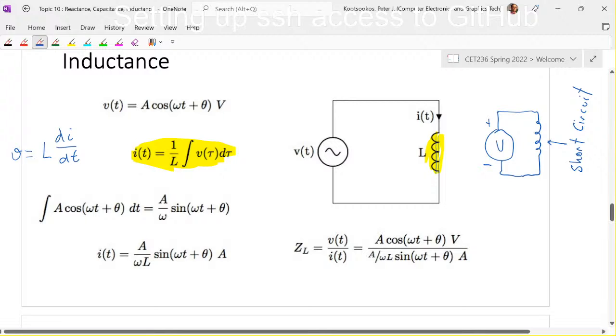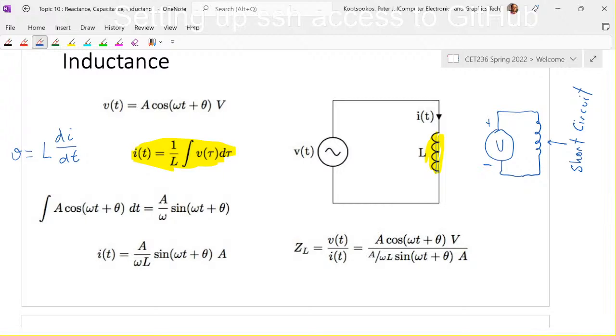And the coil is connected to the distributor, and the distributor is the thing that sends the spark to each of the spark plugs. The way that spark gets generated in older cars, it's done electronically now, but the way it's done in older cars is through a thing called points. Right? And points are nothing more than two pieces of metal pressed together that all of a sudden are made to pull apart.